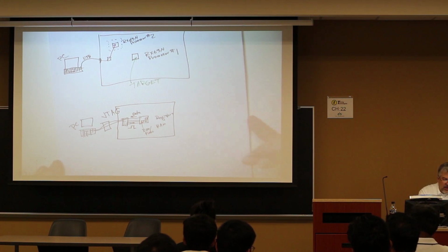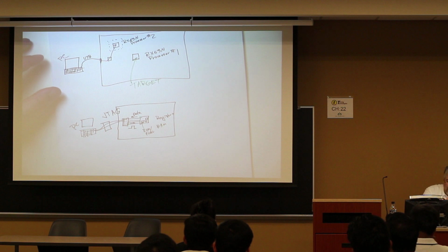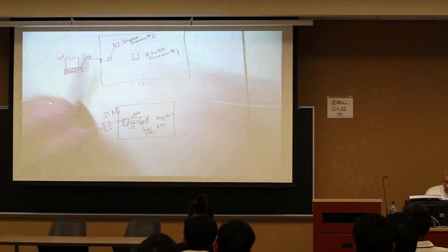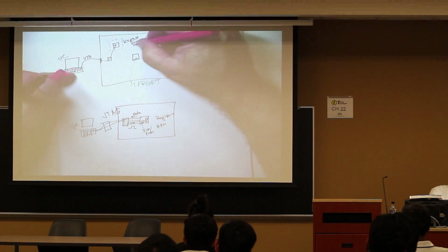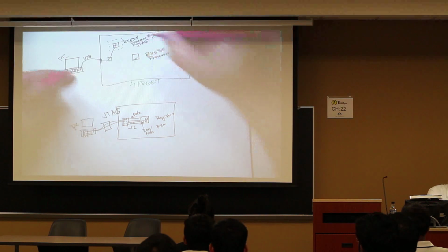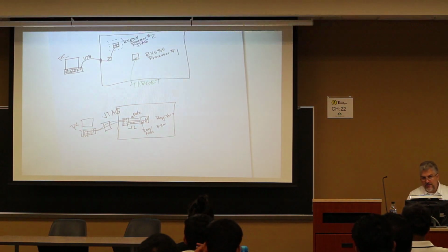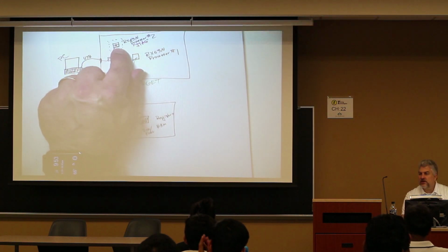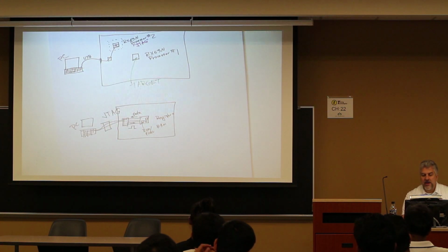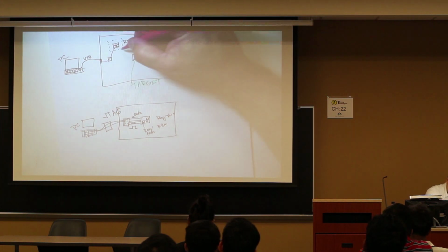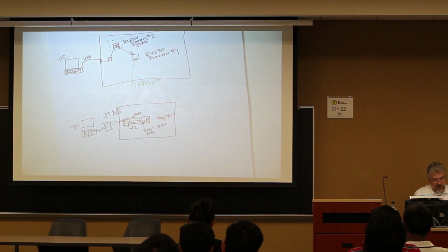And another way, which they do here, is the USB connected to this processor over here is equivalent to our JTAG. In other words, that processor over here is running a special program that you never write. You can download a new version of it, but you will never write that code for that processor. And it will allow communications between this extra processor via the tools.